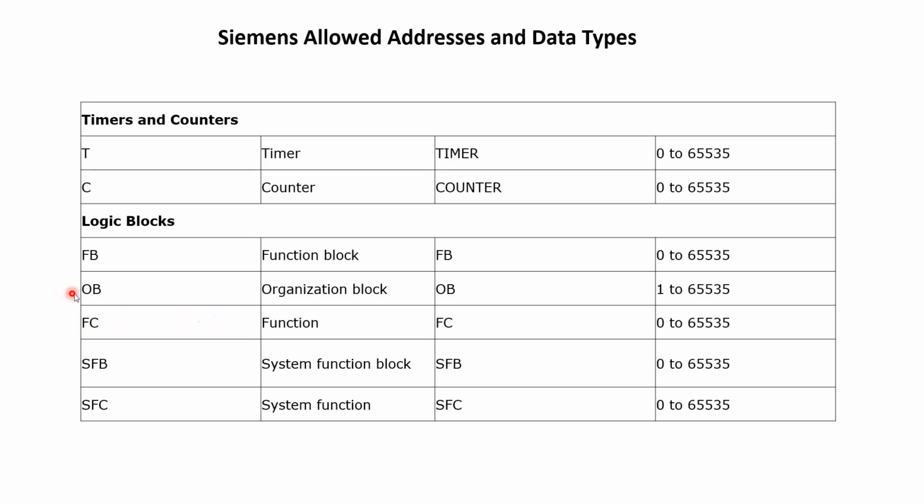All right. Then OBs, like we've seen in our previous lessons, we were programming OB1. OB1 falls under OBs, organizational blocks. It is the main block that is cyclically executed by the CPU. We also have so many other OBs. We also have OB100, which is very important to us, and OB101. Those are your startup blocks. I still need to make a lesson about those ones. All right, I hope you guys are following.